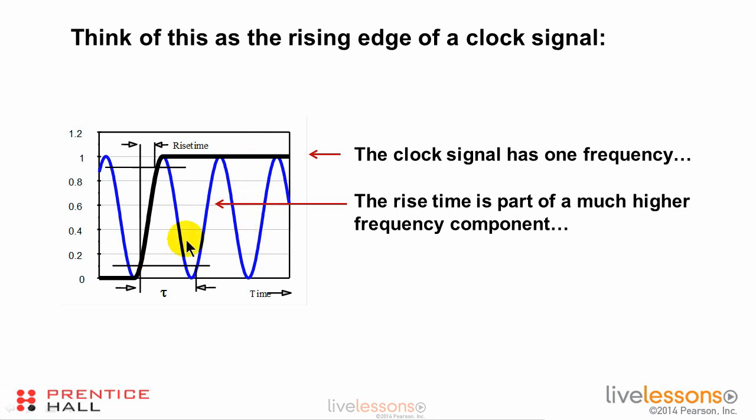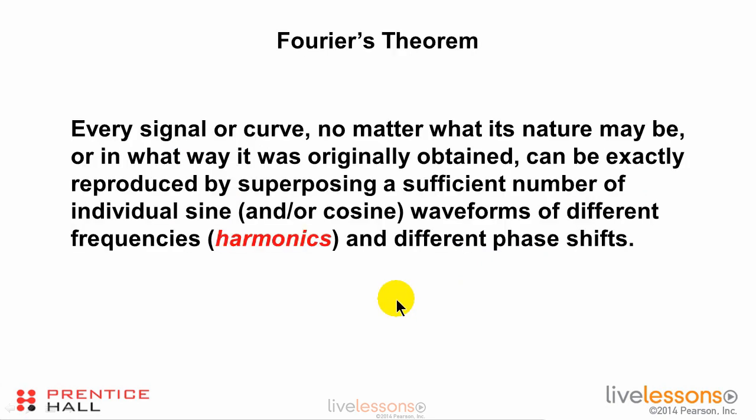But we can think of this frequency right here, this waveform, as an integral part of the circuit because this rise time lies right along the edge of this. So we can consider that at least part of this signal is inherent in the clock signal that we're looking at. So this rise time is part of a much higher frequency component or harmonic of the fundamental signal.